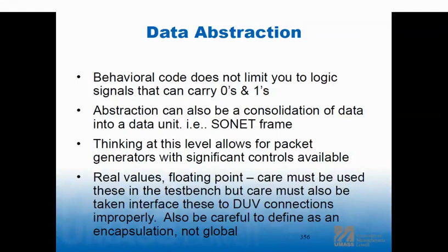But what if I want to verify a processor? What I need there is a generator of random instructions. So I have something that generates legal, maybe most of the time legal, instructions. And every time the program counter goes and gets something, I take a random next instruction out.